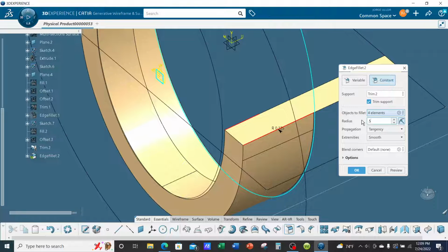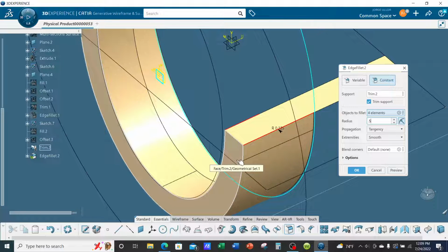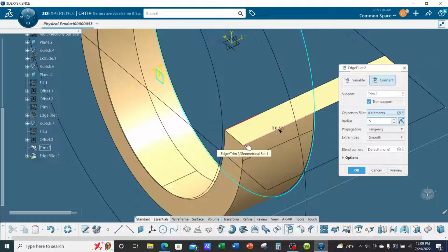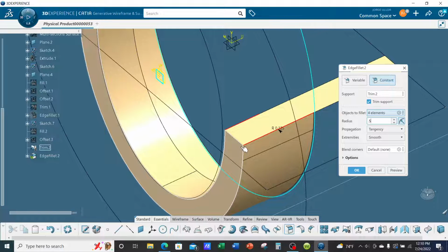Now the radius of the end mill is 1/2 inch. Typically you want to go a little higher, because as the end mill is machining and it stops to make the turn, it's going to chatter, it's going to bounce off of the material and maybe leave a few dents on that radii. So typically you want to go higher, just keep that in mind. Maybe go 0.5 plus 1/16 or 0.5 plus 1/32 to force the drill to make a turn along an arc and not stop and then continue cutting. Okay, so keep that in mind. I'll just leave it at 1/2 inch, but typically you want to make it a little bit larger than the radius of the end mill.